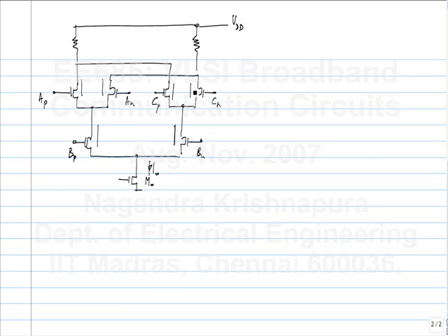Okay. Now, we said that everything is now determined by the differential voltage. Of course, that doesn't mean the common mode can be absolutely anything. Usually that means there is a certain range. So let's evaluate what the range is. So, common mode limits. Okay. This whole action works very well assuming all transistors are in saturation under all conditions.